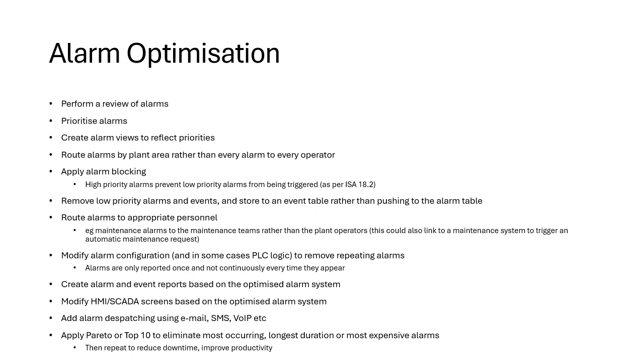I think a good guideline is 2 or 3 alarms per hour. If you've got a lot more than that, then that's probably too many. And if you've got less than that, then that's good. But then maybe you could add some alarms because maybe there are events or things you're missing where you could actually respond to those to improve your operations.